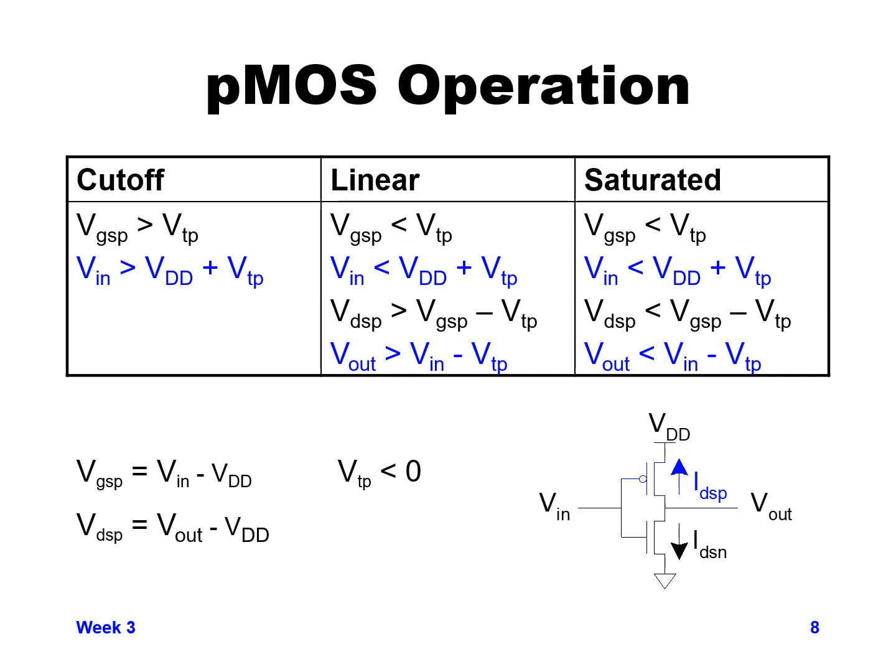For linear operation, Vn has to be less than VDD plus VTP. Again, keep in mind, VTP is a negative value, so Vn has to be less than some value which is VDD minus the absolute value of a threshold voltage below VDD. As long as Vn is lower than VDD by enough, you start turning the transistor on and you're in the linear region, as long as Vout is greater than Vn minus VTP.